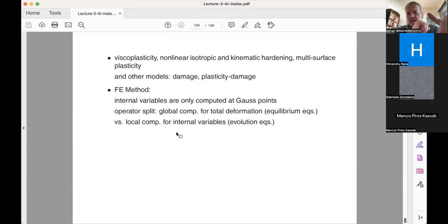The final word is that when you do the computation with J2 plasticity, the finite element interpolation has to be chosen with care. Namely, you have to handle the locking phenomenon related to quasi-incompressibility, given that the plastic strain is much bigger than the elastic strain, and that the plastic strain with Von Mises criterion is incompressible. That means the total strain is quasi-incompressible. So usually finite element interpolation, for example the constant strain triangle, will be very lousy for plasticity computation, for sure. You have to do something better. We'll also see how to do enhancement when you go into dynamics and things like that.